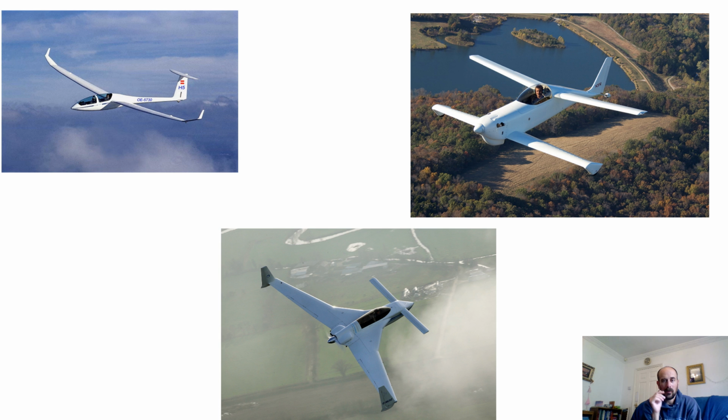But then also, because this is an aircraft and it's got to generate lift, we need the front surface, whichever one that is in the three cases, to be working harder than the back surface. So it needs to be generating more lift per unit area. It needs to be running at a higher CL.